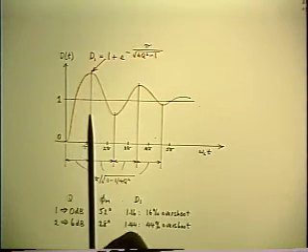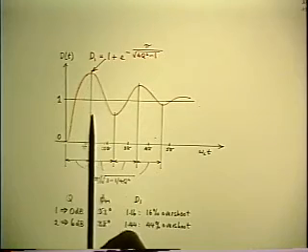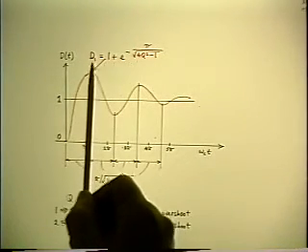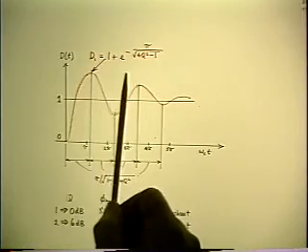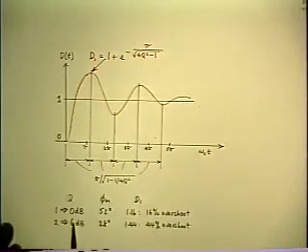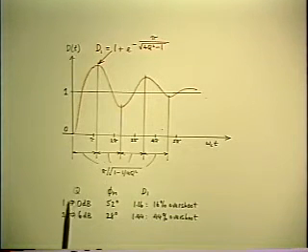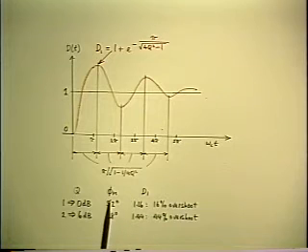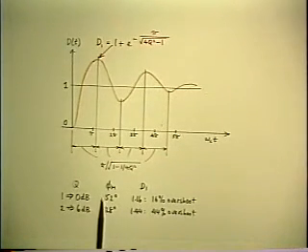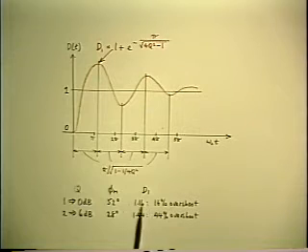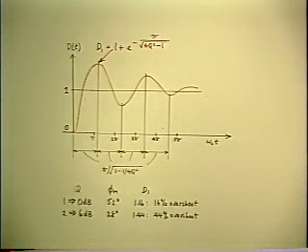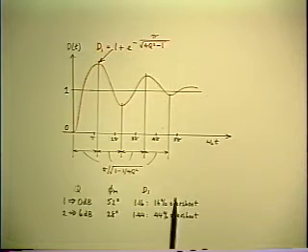And the important part of it usually is the initial overshoot, and you can find that pretty easily. I called it D1, the first peak, and it's a function of Q. And here's its value for a couple of interesting cases. The transition case where Q is equal to 1, corresponding to a phase margin of 52 degrees, gives you a 16% overshoot in the time domain, which isn't that much. That's why it corresponds to the transition case, where a little bit of peaking corresponding to Q of 1 isn't bad.